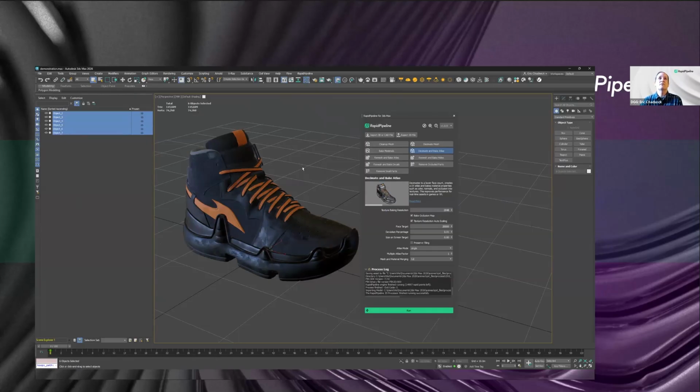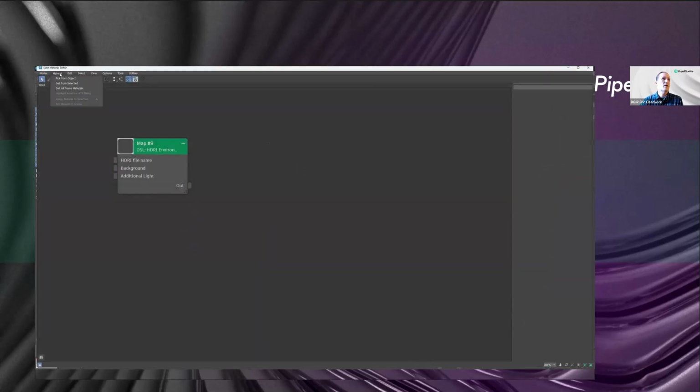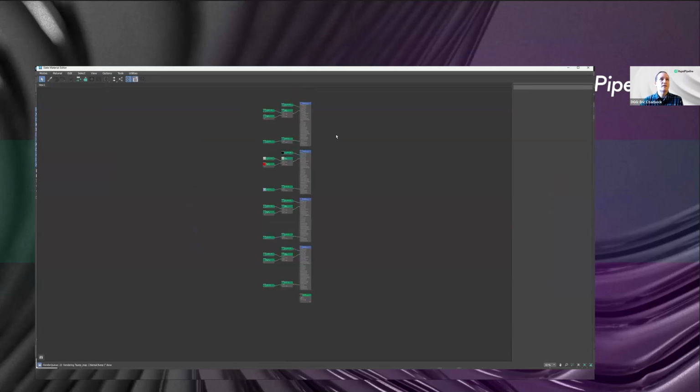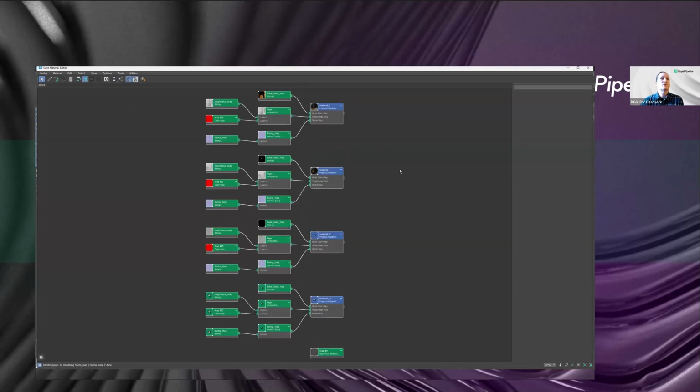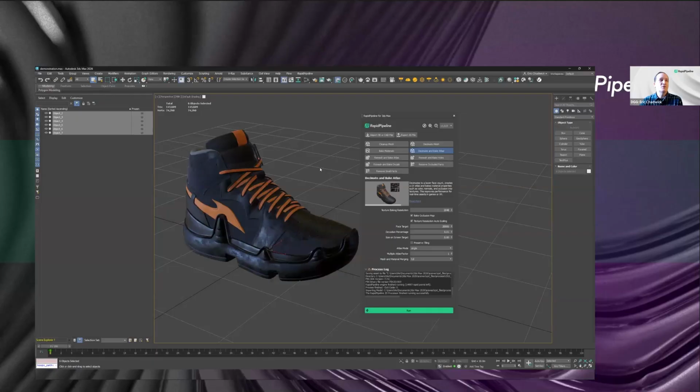And if we pull up the material editor and grab all the materials from the scene, we can see there's 4 materials here. I'm going to collapse them so they're easier to see. So there's 4 different materials here and 6 objects. And generally for the web, for a single item like this, I'm going to want to collapse it down into one material and one mesh node. And that makes it super efficient, makes it one draw call, super fast. It runs really well in AR, and it'd be super efficient.